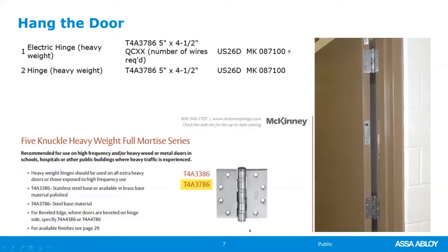The stair doors don't get a lot of use, but they are wide and they are heavy doors. And so that's why heavyweight hinges instead of continuous hinges or something else. Yes, you could use continuous hinges if that's what the owner wants, but there's 4 stair towers on every floor, and then multiply that by 18 floors. That gets to be quite expensive. I'd rather use the money on something else like access control.